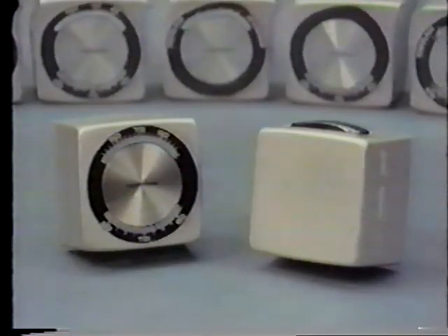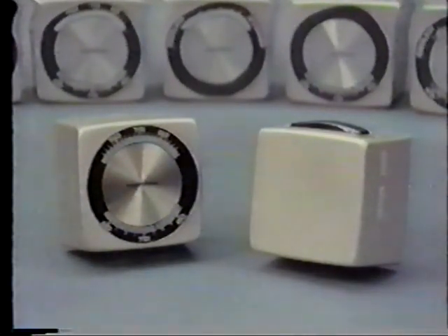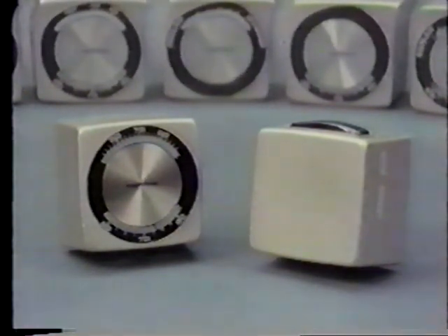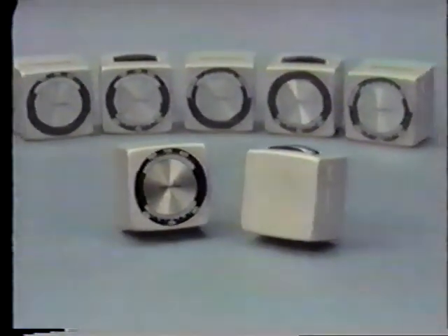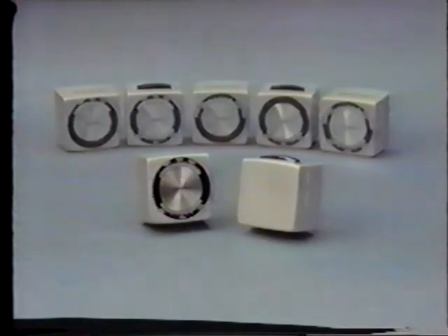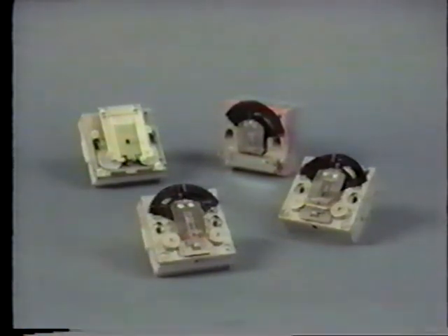There are many different types of thermostat covers available for commercial applications. Most common of these is the blank cover with a concealed set point adjustment and a full dial model with thermometer and exposed set point adjustment. There are a number of other variations of thermostat covers that may be used to meet the requirements of a given application or the specifications of an architect or engineer designing the control system. There are many variations of thermostats available, and you've seen just a few, namely the two-pipe single pressure devices.